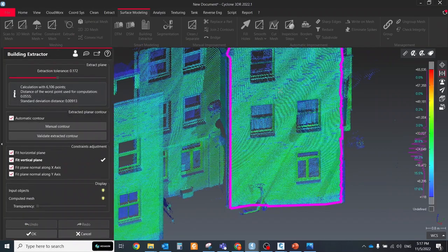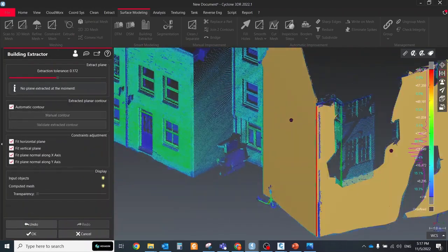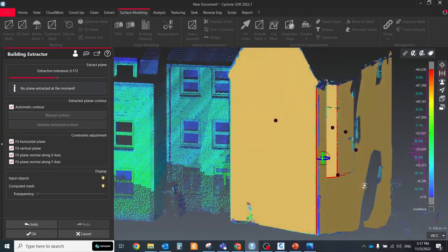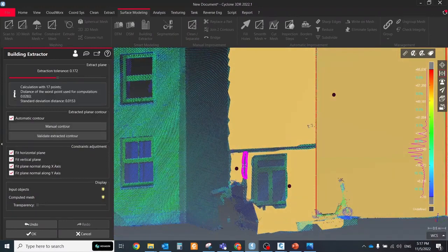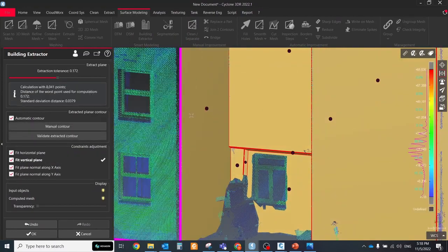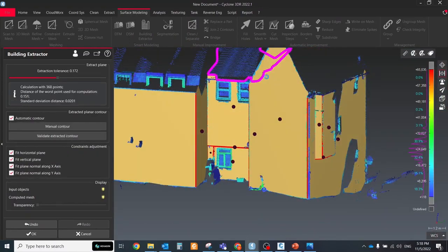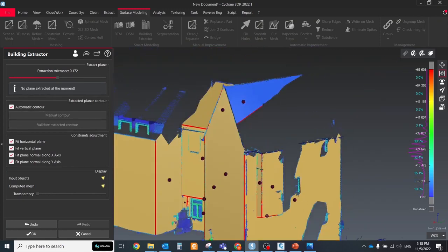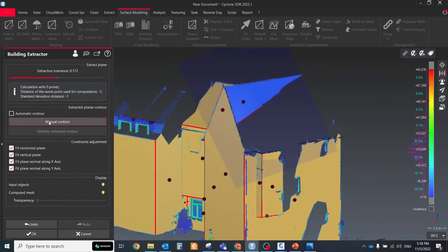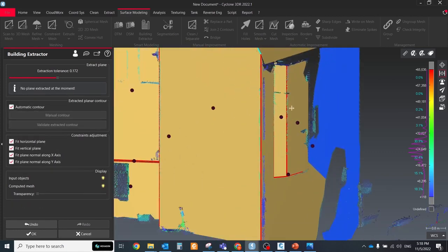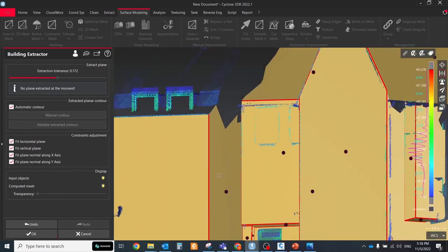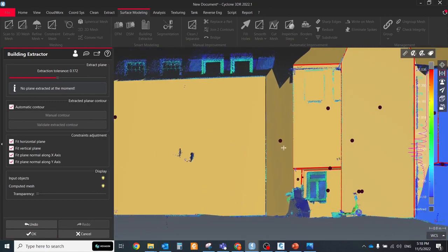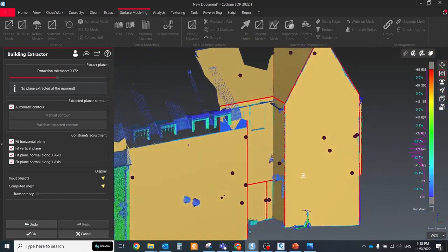This command allows you to create a simplified mesh based on planar parts of point clouds or a mesh. Click on the input object to extract planar areas and contours, then validate the extracted planar contours; this will create a planar mesh. Repeat both operations to create planar meshes as needed. The connections between the extracted planes are calculated by default. However, you can force or remove some connections. To do so, drag one ball representing a plane onto another one to force the connection. In order to remove a connection, select the edge representing the connection and press the Delete key.